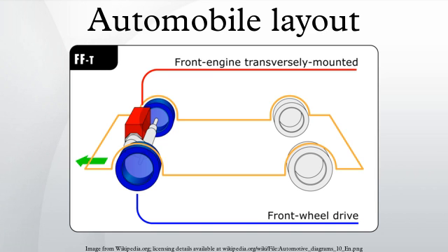Characteristics. The vast majority of rear-wheel drive vehicles use a longitudinally mounted engine in the front of the vehicle, driving the rear wheels via a drive shaft linked via a differential between the rear axles. Some FR layout vehicles place the gearbox at the rear, though most attach it to the engine at the front. The FR layout is often chosen for its simple design and good handling characteristics. Placing the drive wheels at the rear allows ample room for the transmission in the center of the vehicle and avoids the mechanical complexities associated with transmitting power to the front wheels.